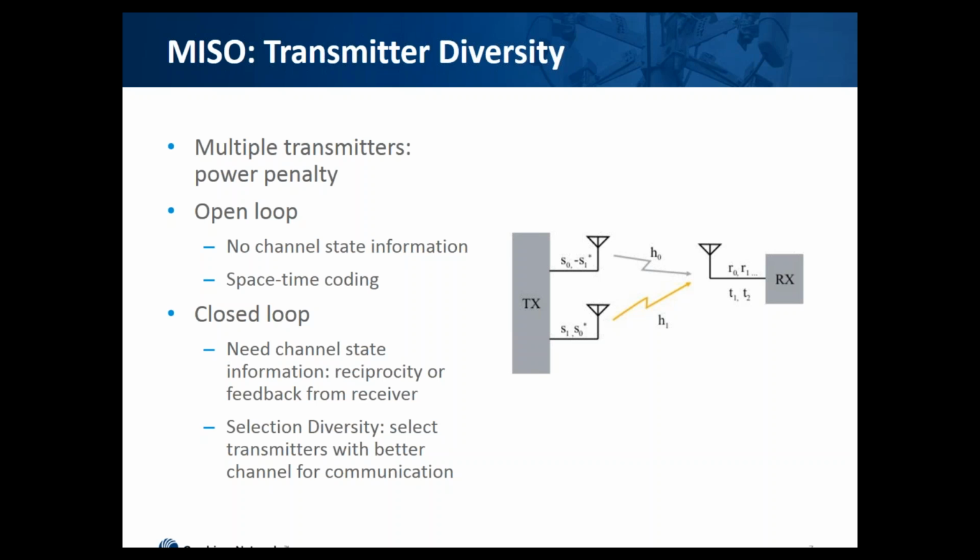Note that we have not increased the throughput in this case. It is true that in the first transmission we sent both S0 and S1, so two waveforms instead of one, but in the second transmission we have repeated the same two. We use two transmissions for two waveforms, which is the same speed we were using in SISO systems.